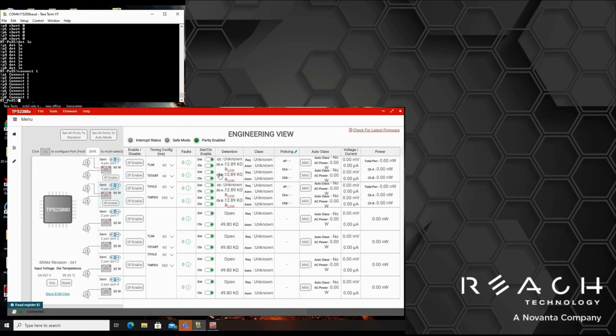And depending on your PSE, if you have asymmetric loads, or you can set loads such that load only appears on one pair, or goes out of balance, or things like that. You can draw any amount of power available, regardless of class. So you can make sure that when you go outside of a class boundary, it catches that.